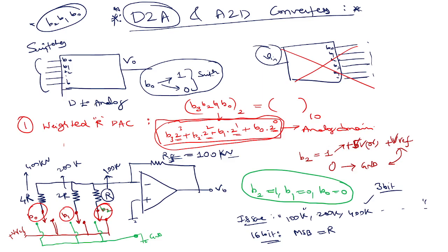By now you already know why it is MSB. So the MSB resistor is R, then your LSB resistor is what? Like R, 2R, 4R, like this is 4R, which is 2 power 3 minus 1, correct? So your LSB resistor is 2 power n minus 1 into R.